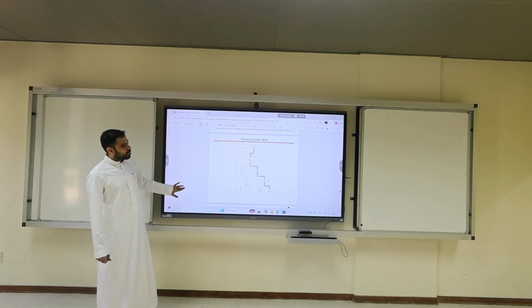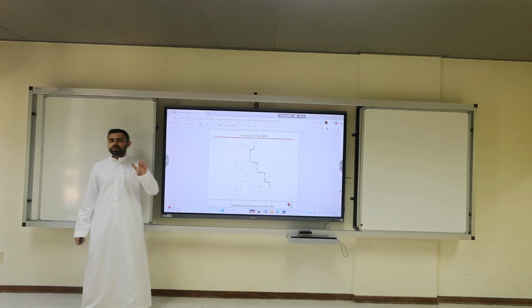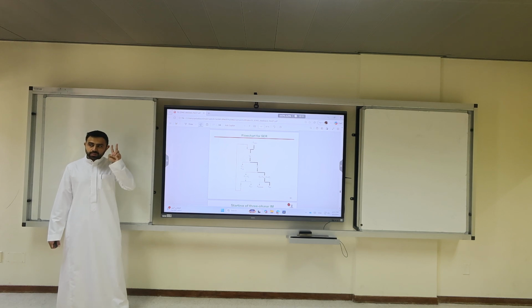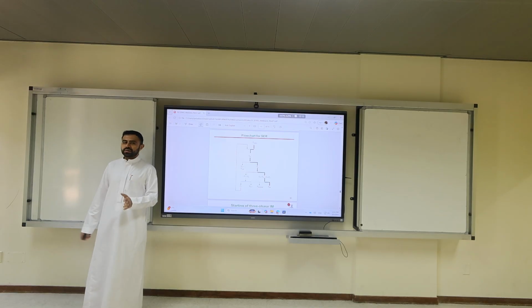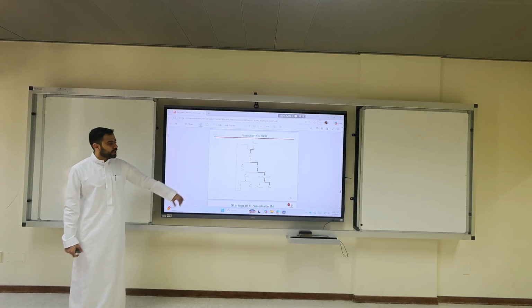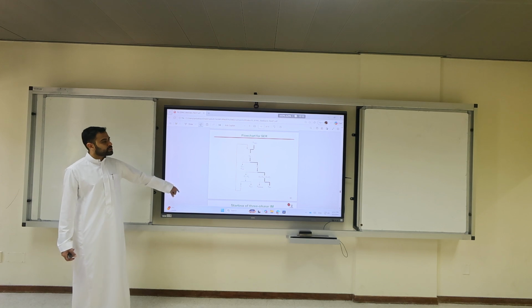So enough about control. We're done with the 6 control techniques, okay? The two important ones are slip energy recovery, if you want to control the wound rotor, and the V over F, which is the majority of induction motors, if you have squirrel cage, or if you want to apply your control from the stator. The vast majority of control schemes use variable speed drives, and it uses V over F directly. Okay? So V over F, I can say, is probably the most important way to control the vast majority of induction motors.